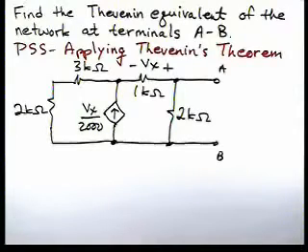If we look at step 2B of that strategy, it says if the circuit contains only dependent sources, and our circuit here only contains dependent sources, an independent voltage or current source is applied at the open terminals, and the corresponding current or voltage at these terminals is measured. The voltage-current ratio of the terminals is the Thevenin equivalent resistance. And since there are no independent sources, then the open circuit voltage is 0.